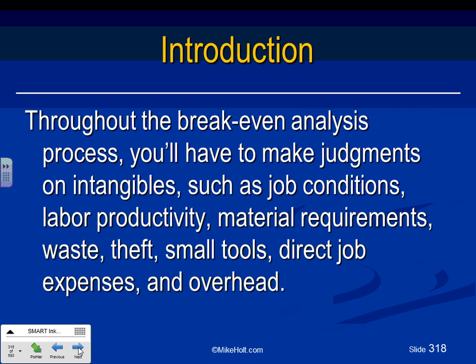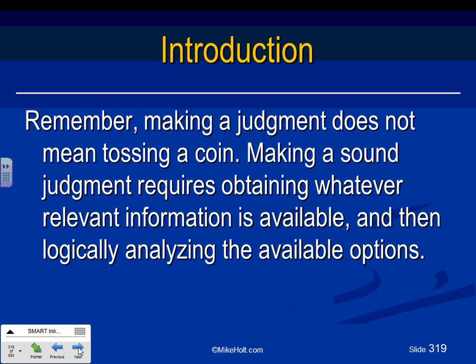When you guys go through the break-even analysis process, you have to make some judgment about intangible things: job condition, labor productivity, material requirements, waste, theft, small tools, direct job expenses, overhead. After you get your break-even, you can add or deduct based on all these conditions.